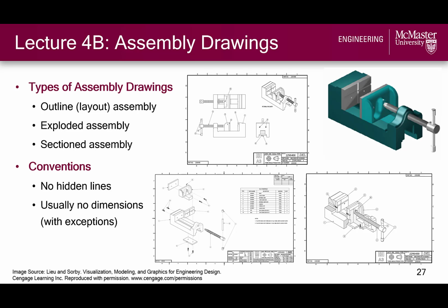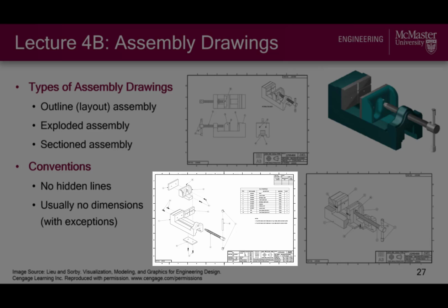However, in some cases, we may want the assembly drawing to illustrate how a device is put together, and that's where the exploded view comes in. The exploded assembly drawing shows the device in a disassembled state, which may be helpful in seeing all parts of a device in a single isometric view, and it can also elucidate how those parts fit together, which is important information for product manufacture and even for maintenance.